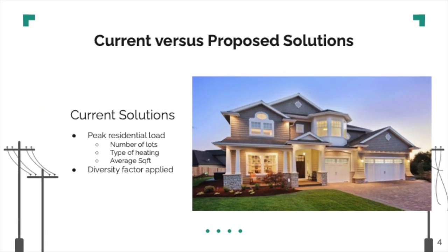The current solution for this tool is to calculate peak residential load based on the number of lots, type of heating, and average square footage. Once this is done, a diversity factor is applied to simulate a realistic peak load.